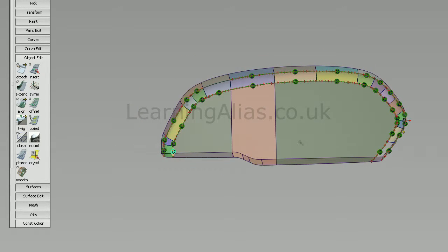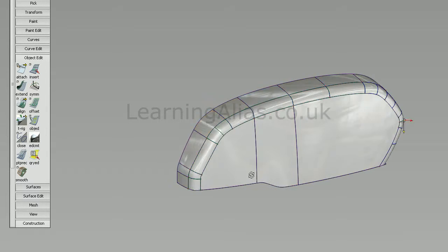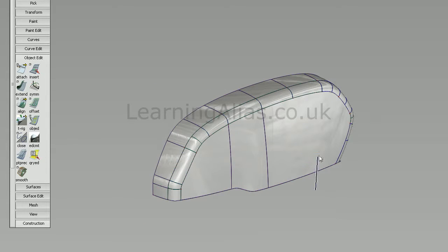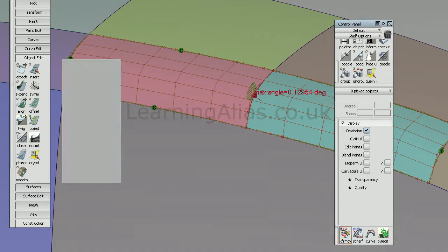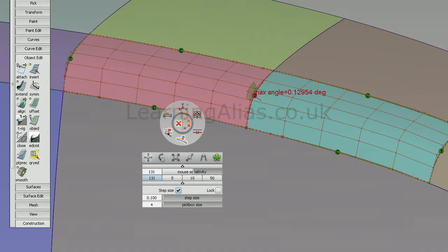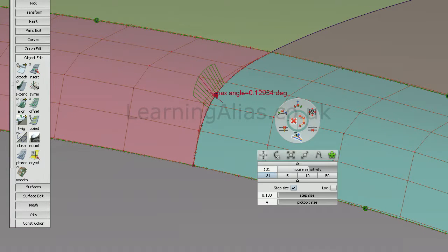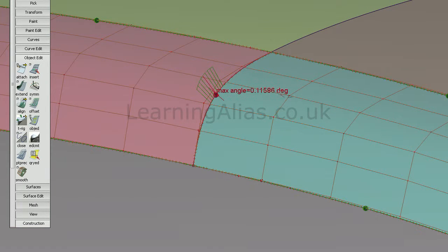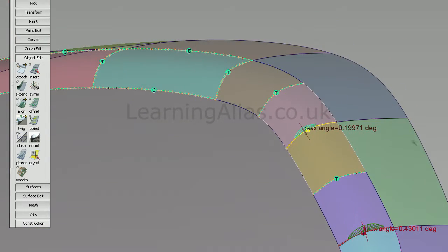The evaluator showed us we've got G2 continuity for the top and side boundaries of our shoulder surfaces. We now need to check for G1 or tangency continuity along the shoulder, so in this direction. Part of the construction requirements were curvature throughout the main surfaces and tangency on any sort of blends or fillets or rad surfaces. Some employers will ask for curvature throughout the model, some will only require tangency, but this was the requirements for this particular build.